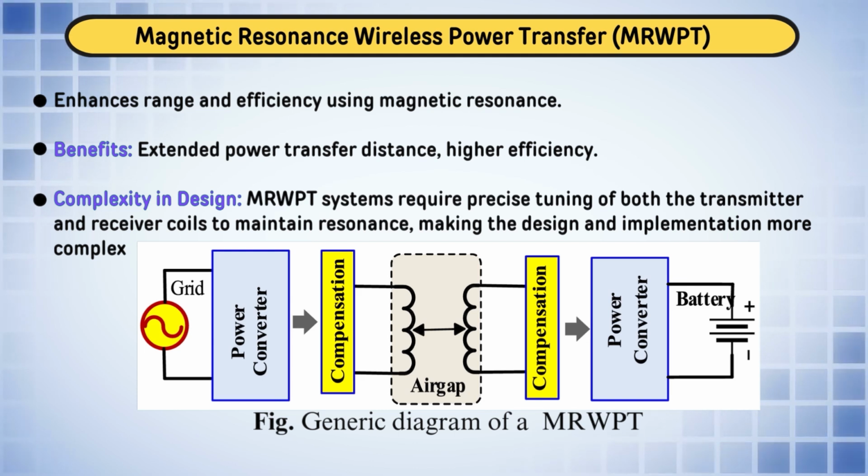Similarly, in the case of the boost converter, when the switch is on, the inductor stores the energy, and when we release the switch, the diode will be in forward bias, and this inductor energy is stored in the capacitor, and the capacitor further releases the energy to the load.